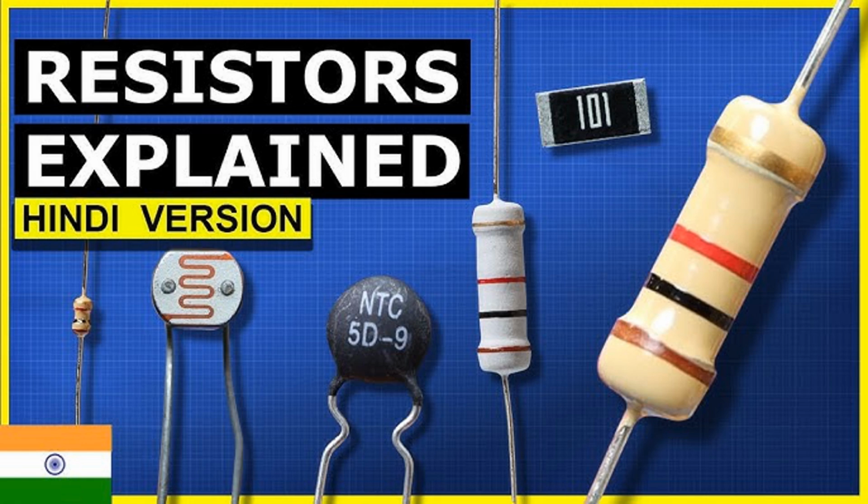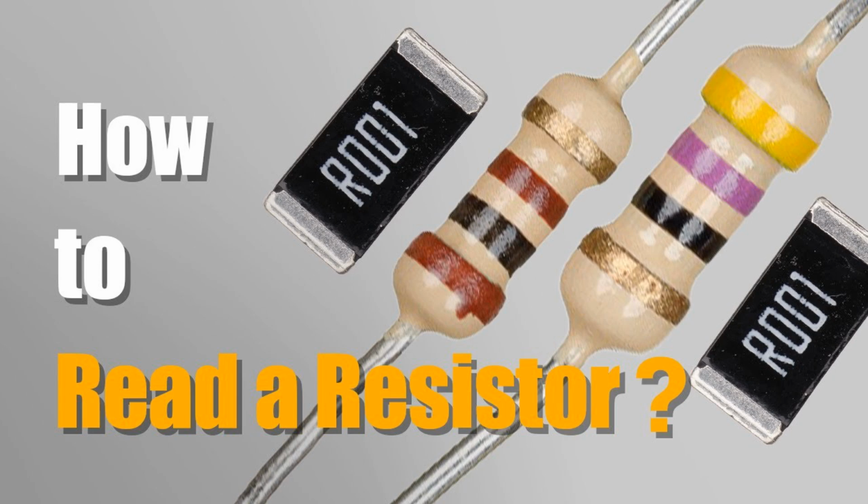Example. The I2C bus requires pull-up resistors on the SDA (data) and SCL (clock) lines to ensure they default to a high state when no device is pulling them low. Logic gate inputs. Purpose. Logic gates with floating inputs can exhibit unpredictable behavior. Pull-up or pull-down resistors ensure that unused inputs are in a known state. Example. An AND gate with an unused input can have a pull-down resistor to ensure that the input is low, preventing unintended output states.